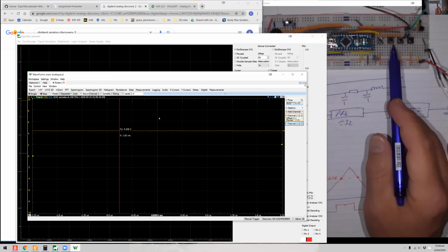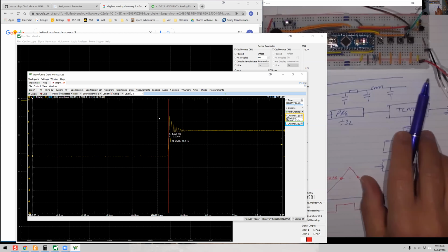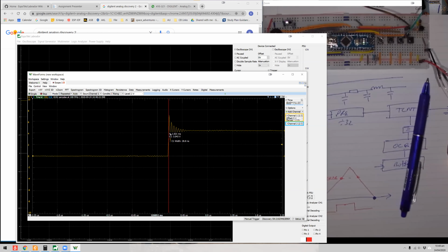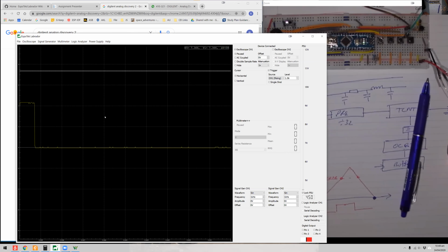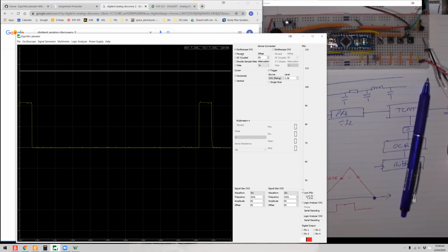And every time we punch this oscillator with a waveform, like a change from 0 to 5 volts, it starts oscillating, and then it slowly stops oscillating down here. Now, you can't see that, of course, in this circuit. You can see that something's happening, but you can't measure it. And this is the limitation of our sample rate for an ADC. You're missing things that are there.